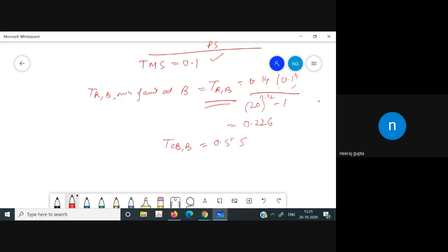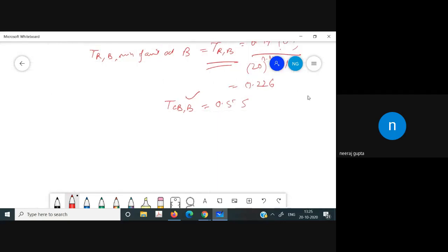Now, as we have done in the previous case, the expected operating time of RA should be greater than the sum of the two, plus 10% of this sum to take into consideration the overshoot.